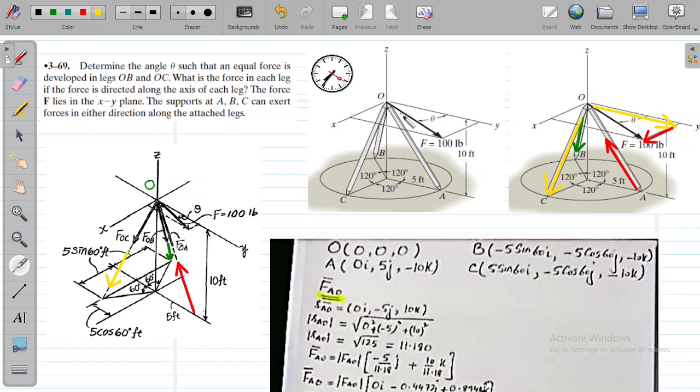This is one force over here, and you have got the other three forces, 1, 2, 3. They are basically non-coplanar but concurrent in nature, because this is a three-dimensional force system. These three forces are acting in a 3D plane but they are concurrent, and since it's a 3D plane, we'll call it non-coplanar. But this force is acting in a 2D plane, and we can say it's a coplanar force system in which this force is acting at point O. So you must understand these force systems, very important.